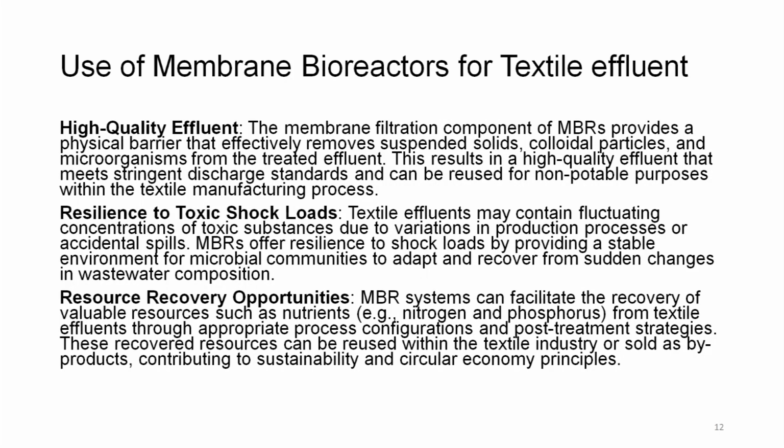High quality effluent. The membrane filtration component of MBRs provides a physical barrier that effectively removes suspended solids, colloidal particles and microorganisms from the treated effluent. This results in high quality effluent that meets stringent discharge standards and can be reused for non-potable purposes within the textile manufacturing processes. So, it gives out treated high quality effluent.